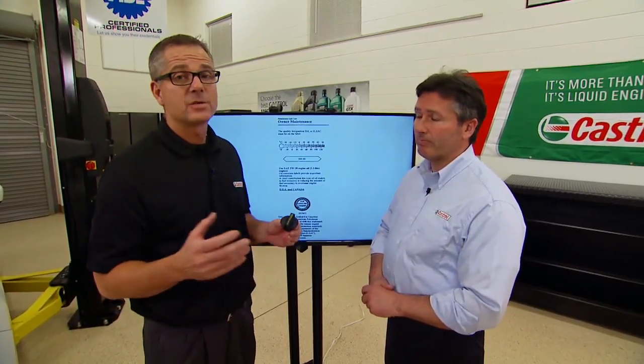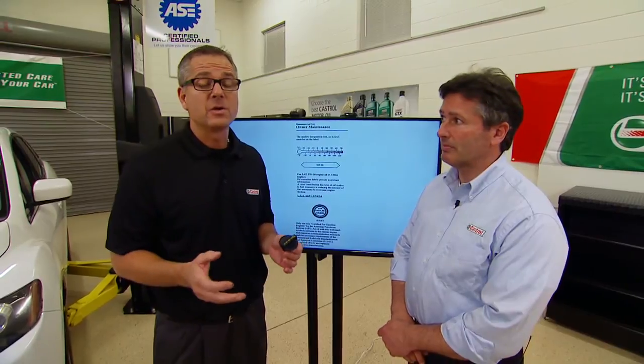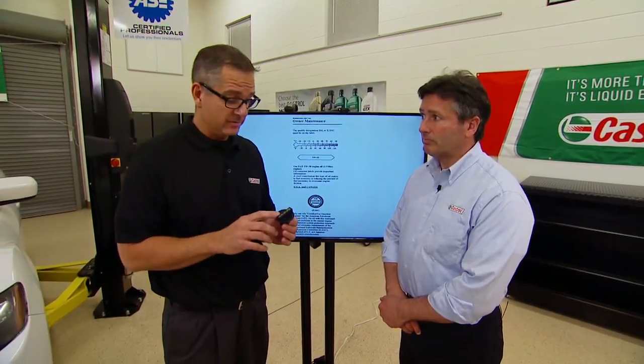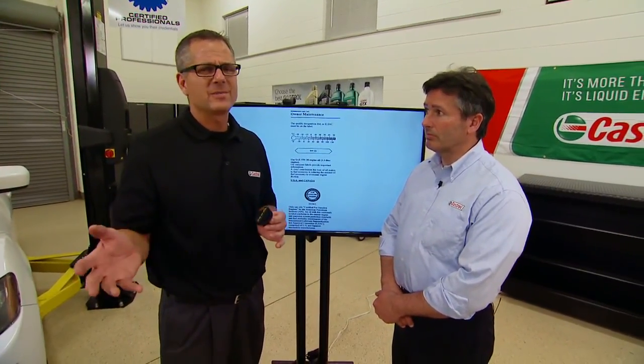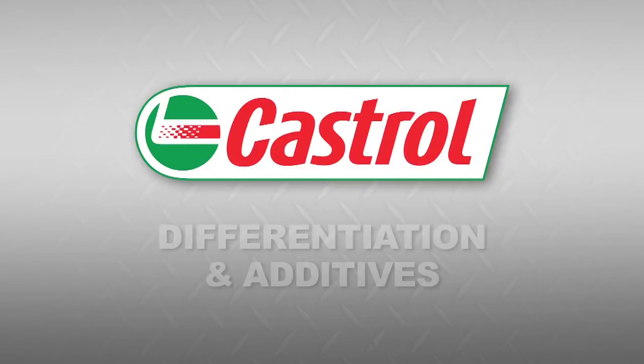So when it's time to change the oil, make sure you get the right oil, the right selections, the right quantities. You can go right to the point of sale. It'll tell you everything you need to know. That system will work every time. If you're not sure, check the owner's manual, the cap. There's several resources, but the key is to get the right oil into the vehicle, whether it's transmission fluid or engines. You could do catastrophic damage if you don't have the right oil.